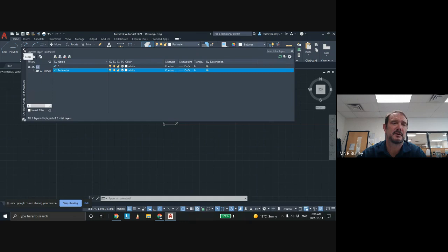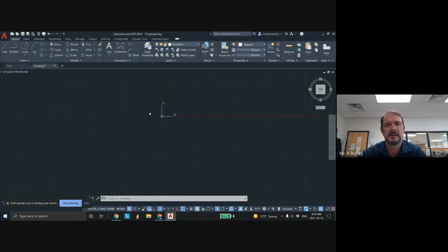So click X out of this thing for a second, and I'm going to come in here and grab my line tool. When I grab the line tool right now, it won't grab a hold of that UCS because there's nothing there. There's nothing for it to grab. So in order to start it at 0, 0, you go 0, 0, 0, enter.